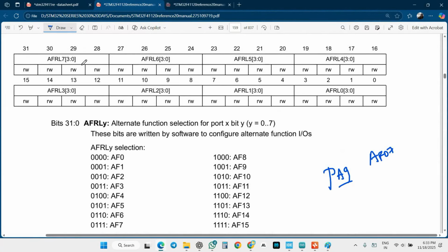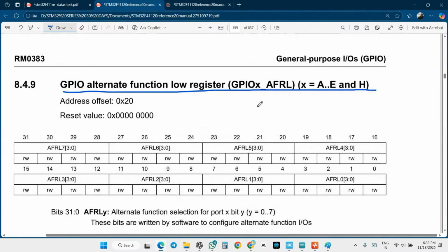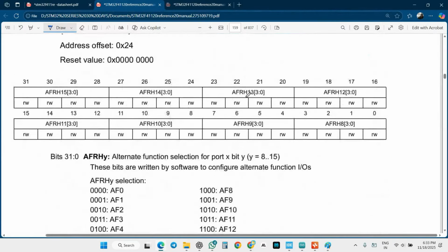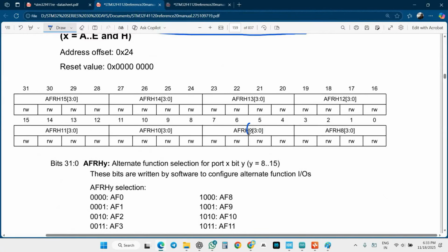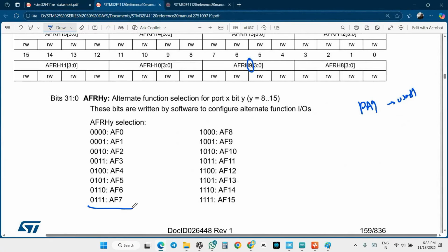It is not providing the ninth pin, so you have to consider whether it has 9 or not. So it is the low function register, no. In this, 9, yes, it is located at the alternative function mapping, because Port A pin 9 is how you configure UART 1. You have the alternative function mapping of AF07. So AF07, it is there. Simply implement 0, 1, 1, 1. That's it, you're going to implement it.